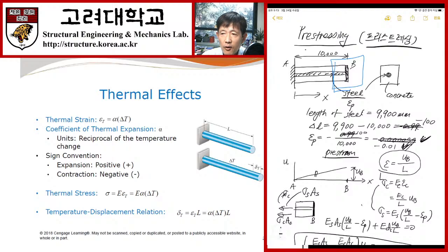Okay? Or you can use the three conditions in another approach. You first define the displacement field, then you calculate the strain, then the stress, and then the internal forces. Then you compare the internal forces with the external forces to satisfy the force equilibrium condition. Okay? So you can choose any method to solve your problems.